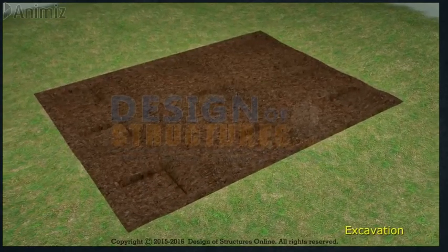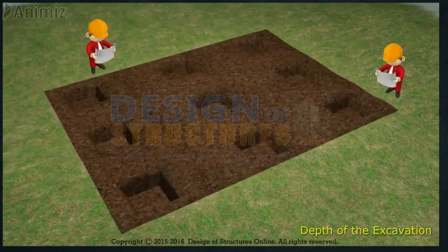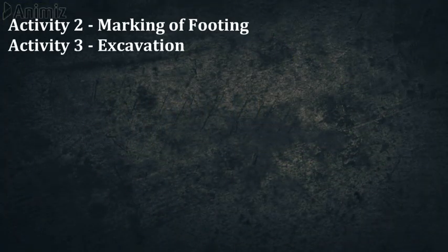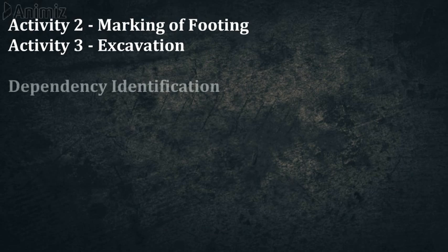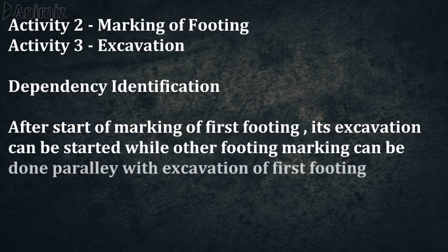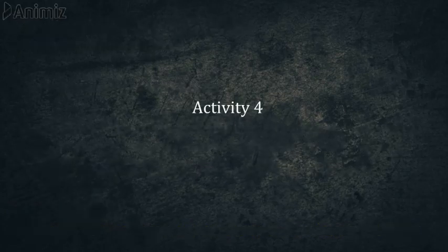Excavation. A structural engineer will be needed to determine the depth of the excavation. So what do we do after marking? We do the excavation. Now the question arises, how is the excavation dependent upon the marking of footing? So here we can deduce a logic that once the marking of the first footing is done, we can immediately start the excavation. So the start of excavation is dependent upon the start of marking. So the next day of marking, we can start the excavation.